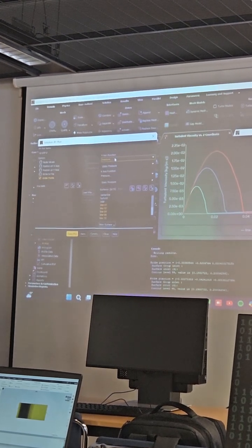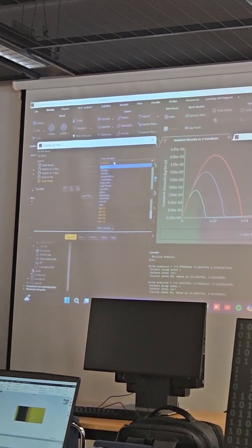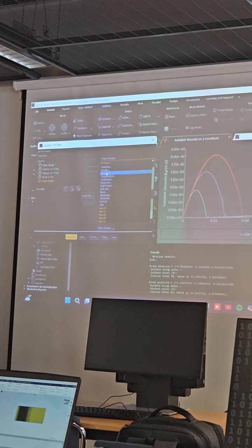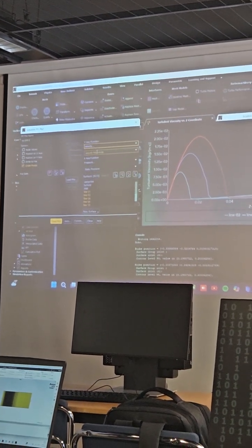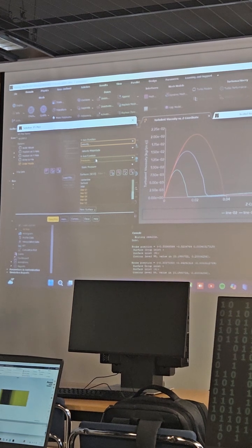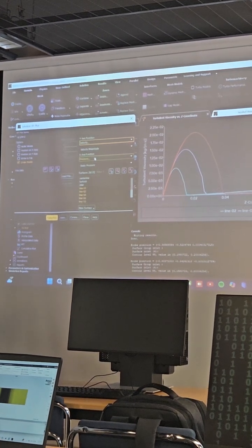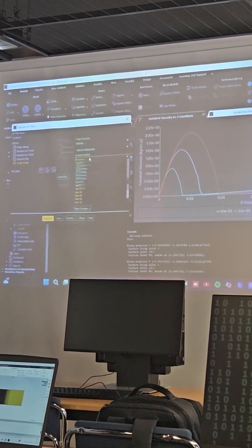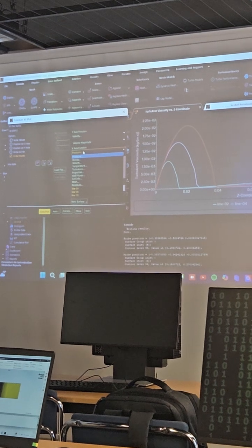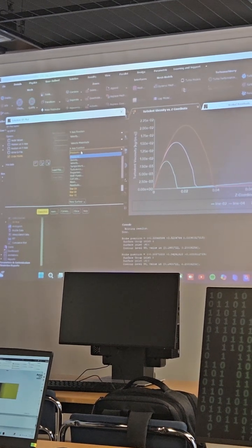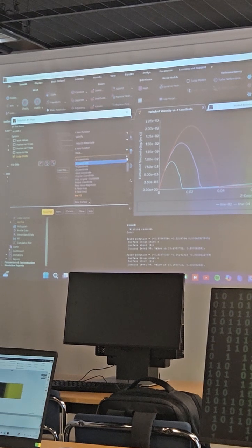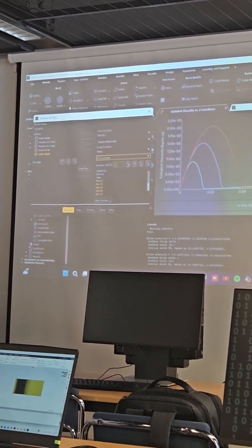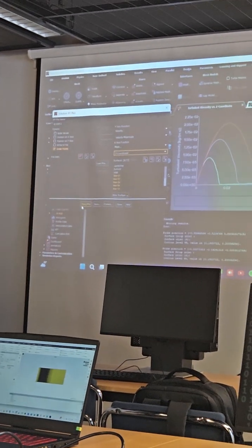So then in the y-axis function, here you can select the velocity. So that's the velocity magnitude. And the x-axis function, so where you want to plot them on, is the z coordinate. So you change from pressure, you go to mesh, and in the mesh you need to select z coordinate. That is the coordinate perpendicular to the plate.